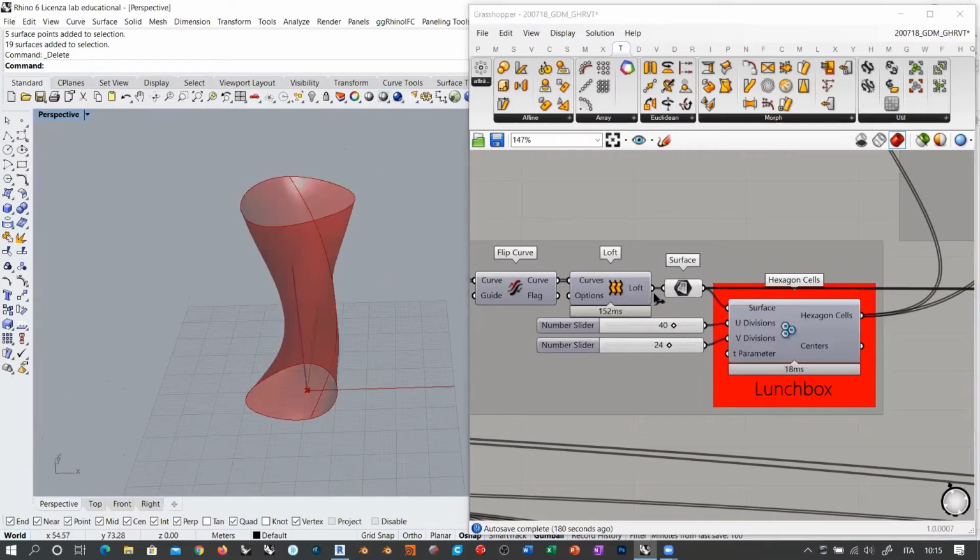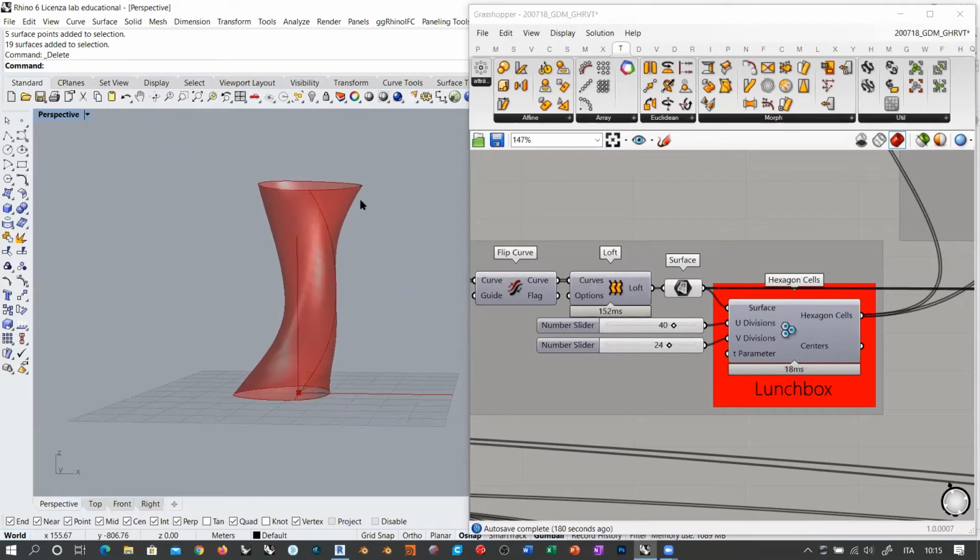And I did this offset of the curves and not the offset of a surface because the offset of a surface depends on the orientation of the surface. So in these upper areas, the surface has this orientation, and so an offset would create a surface like this. So the top edge of the two surfaces would stay at a different height. Okay, and also here at the base, this is the orientation. The offset surface should be something like this, and you will have a different height for the skin and the actual tower inside. So that's why I prefer to offset the curves.